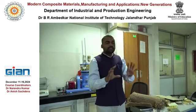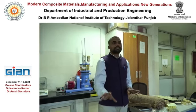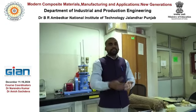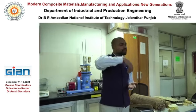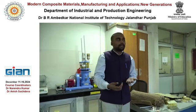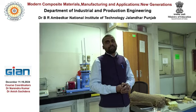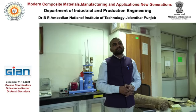We can have such structures, and they are commercially produced, where multiple layers of yarns in, let's say, the 0 direction, multiple layers in the 90 direction, and multiple layers at a bias angle, let's say 45 degrees, are laid and stitched together using needles. These structures are in production and used in a variety of applications, and windmill blades are one of them.